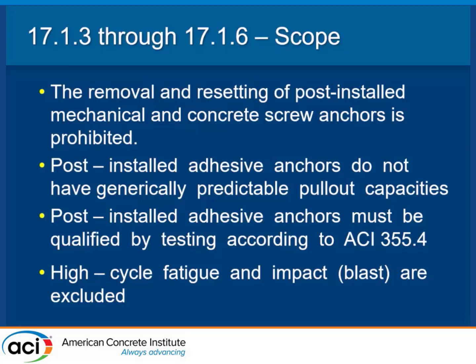All right? We have a beautiful picture when we're trying to explain the certified installers, of when you put the epoxy in the hole, and they had this camera on a group of workers, and they were trying to do such a good job. They filled the hole with epoxy, and they put the anchor in, and they took it out to make sure it was all covered, and they shoved it back in again. And meanwhile, all this epoxy is just going everywhere. And it's just like, no. So in general, you can't install it, uninstall it, and put it back in again.